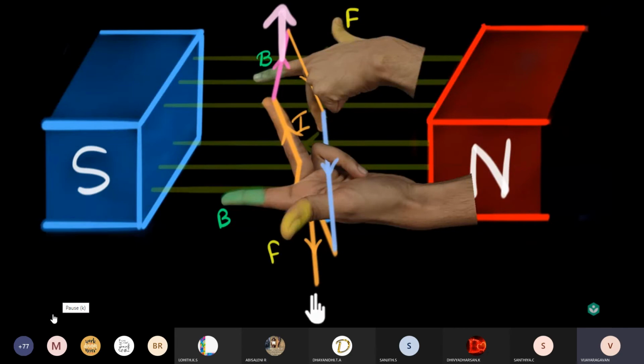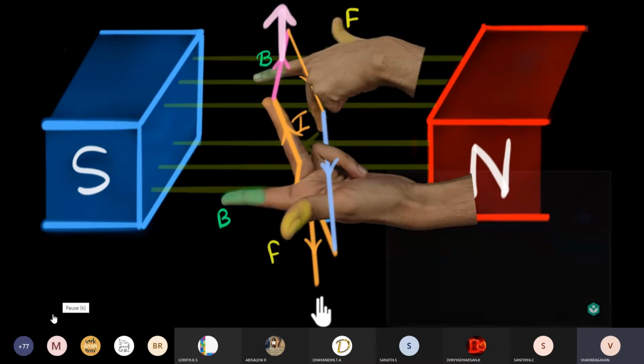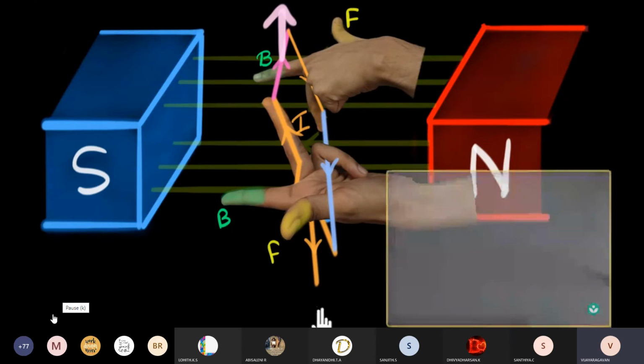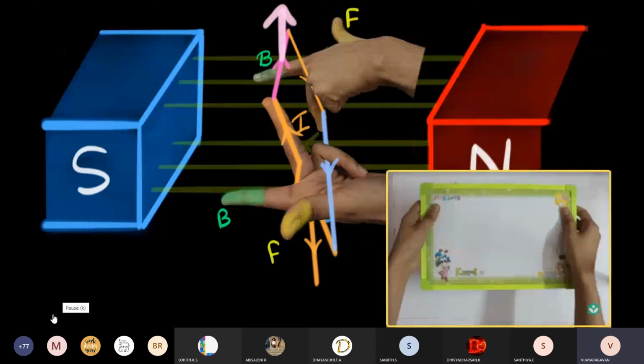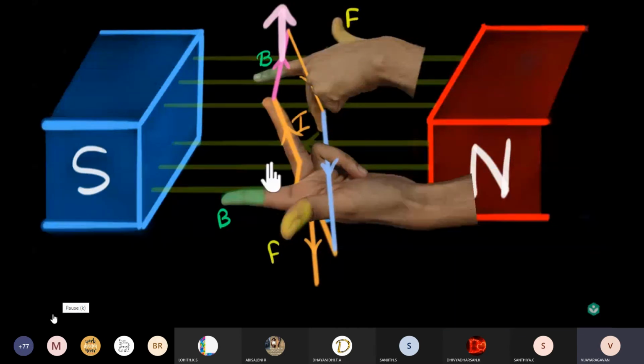It's just like taking this board and pulling it like this. These two forces are not going to do anything. They're just going to cancel out. They're not going to provide any rotation. And as a result, we can totally ignore these forces. They will not affect our rotation at all. So throughout the entire rotation, we will ignore the forces acting on this side and this side because they're just going to cancel out. So yay, our coil is now spinning.